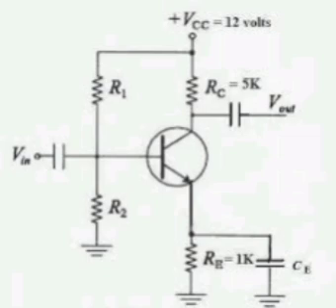At half scale reading of the meter, Im equal to 0.5 IFS and Rx equal to RH, then 0.5 IFS equal to E RH by R1 Rm plus RH into R1 plus Rm. Dividing equation 1 by equation 2 gives S equal to Im by IFS, that equal to Rx into R1 plus Rm whole by R1 Rm plus Rx into R1 plus Rm. Usually R1 is very large as compared with Rm, and therefore S equal to Im by IFS, that equal to Rx by Rm plus Rx.